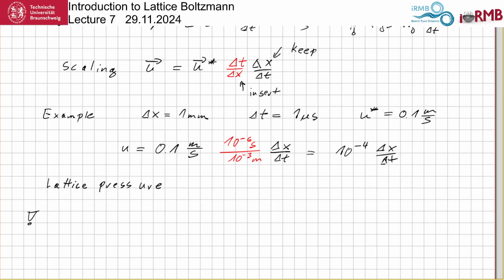So in Lattice Boltzmann, okay, let's say actually the pressure is the second moment. Yeah, it's the trace of the second moment. That's the actual physical pressure. However, in Lattice Boltzmann, this trace of the second moment is by means of the equilibrium always related to the zero moment, because we have a fixed temperature. Yeah, because we have a fixed temperature, the pressure only depends on the density.